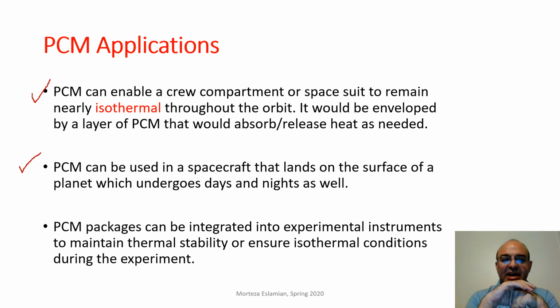So PCM can be used in such cases because there is a very huge temperature difference when the spacecraft is exposed to the day of a planet compared to the night of a planet. It's a huge difference in the thermal load that would essentially need a very complex thermal solution. So PCM materials probably can be used in this case as well, storing energy during the day of the planet and then giving it to the components during the night of the planet.